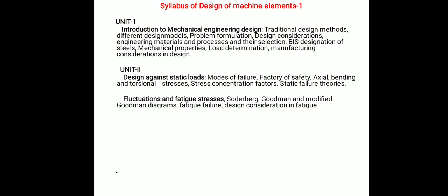Therefore, here in this fluctuation and fatigue stresses, we will study the concept of the endurance limit, up to which endurance limit is the point at which the material has to be designed against an infinite number of cycles. Means it is nothing but beyond that the material will fail under fatigue loading.